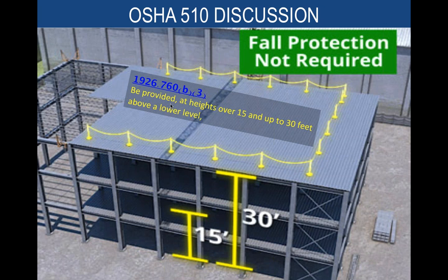Okay. Also, hazardous materials. We have to check the job site locations, right, for highly flammable materials, volatile materials, corrosives, explosives, the hazard materials that any type of employee may come into contact with. Perfect example is compressed gases, right? Acetylene, oxygen, propane. Remember, folks, acetylene is often a significant risk in a steel erection job because acetylene is being used with oxygen as a fuel and a gas setup in order to do welding.